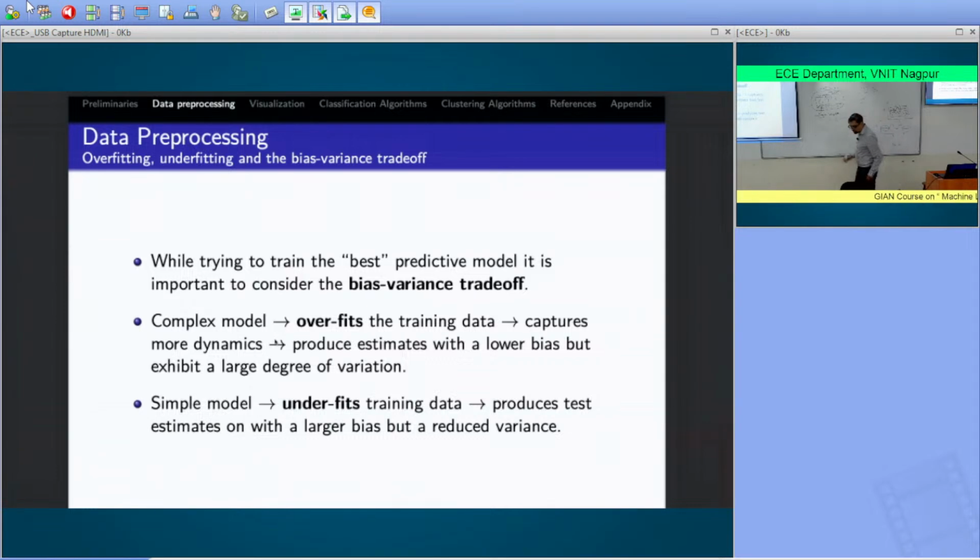Now, because we will never know, when we are estimating a model, we might use a different structure. I'm going to call this S1, and my model is y_t equals alpha 1 u_t plus epsilon_t. Because I never know the truth, this is a very simple example. You probably have a more complex nonlinear system that you would never know, right? So because I don't know this, I assume when I'm building my model that this is what the model is. And from the data, y_t and u_t, I want to estimate alpha 1.